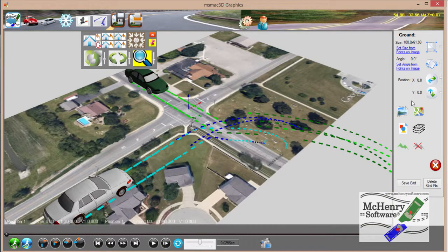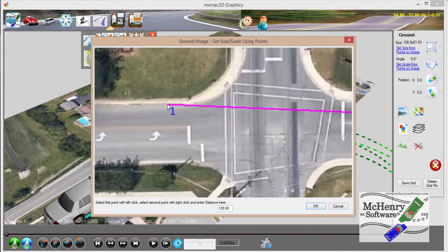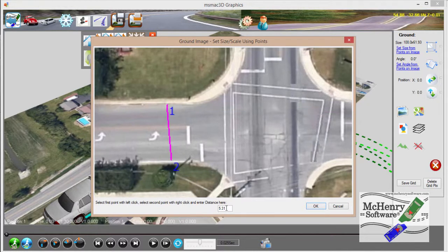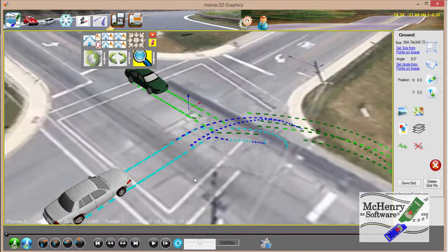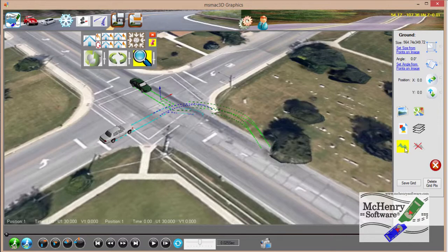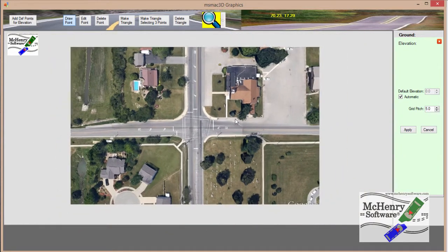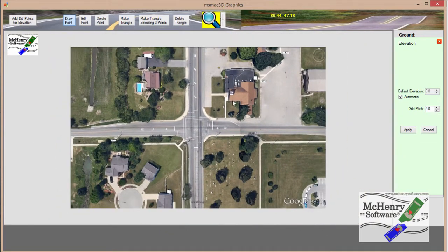But what we're going to do is go ahead and set points from the image. Set this at 30 feet. Now we're going to go down here. That's edit elevation and or remove elevations. We're going to have the edit elevations. Normally I zoom out so I can see the whole plane because you want to do most of them. It defaults to draw a point. So we're going to put some points along the edge of the road here.